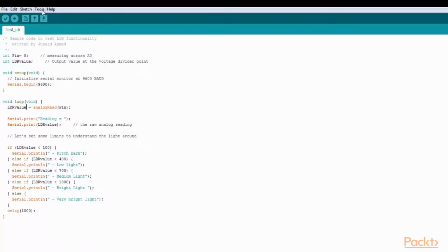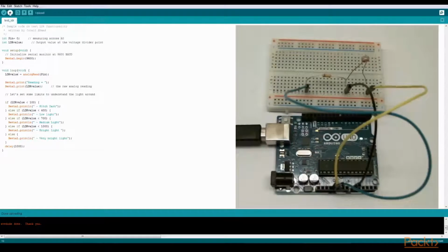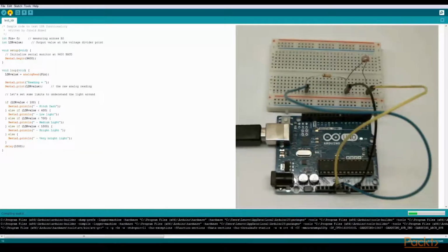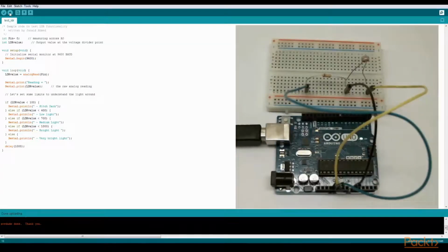Make sure your tools are selected, make sure your COM port is selected, and all that is good to go. I'm directly going to say upload because it's going to compile and upload anyway. This is going to take a second. So it's uploading now, and very good.